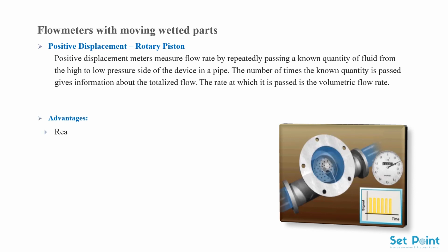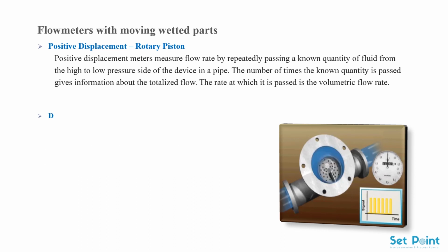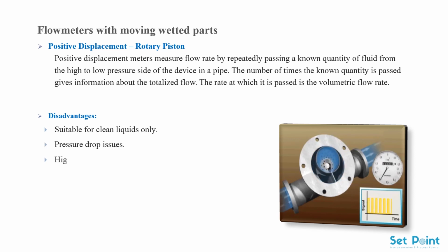Advantages. Reasonable accuracy of 0.1%. Suitable for high temperature service, up to 180 degrees. Pressures up to 7 megapascal. Disadvantages. Suitable for clean liquids only. Pressure drop issues. Higher maintenance costs. Low flow rates.